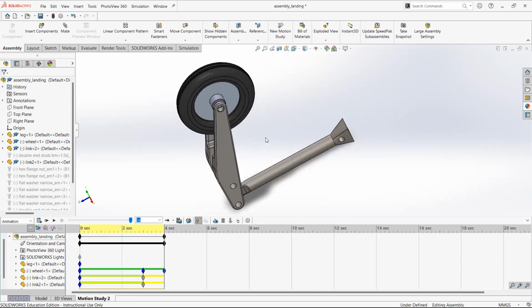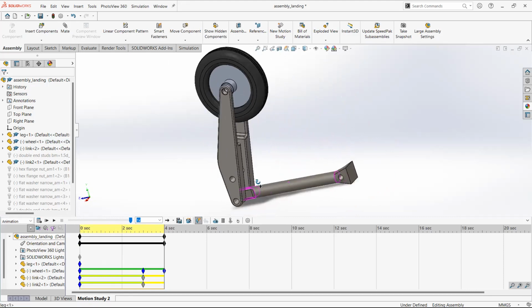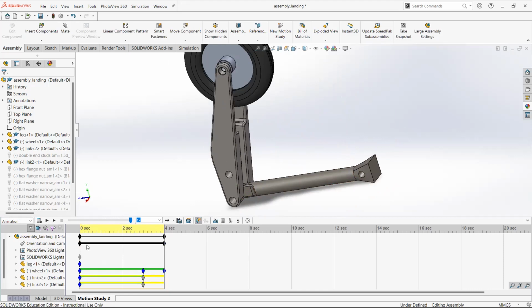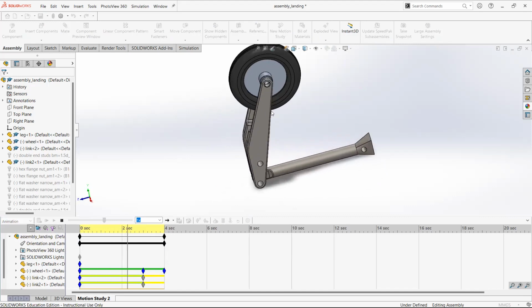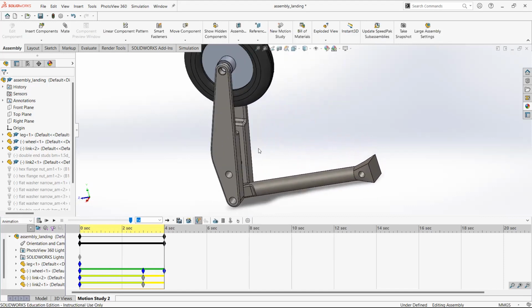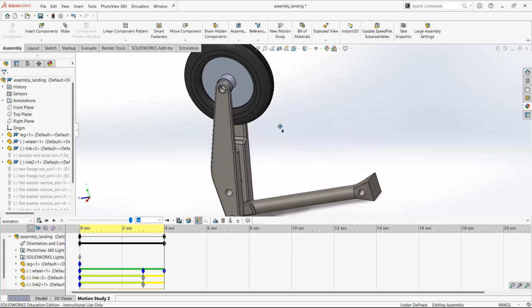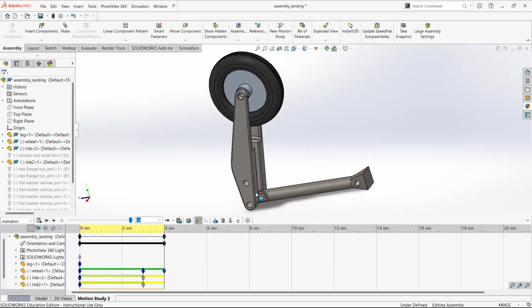So if we right click on this and deselect this, what will happen is that when we move, let's say we zoom in and we move to this view, we see this black bar, which is in the same line as this orientation. So we can know that this action would be done to this part. And when we move the wheels, we saw that this was created and those two links were created since the links were moving with the wheel. So now when we calculate our animation, as it is moving, the camera will also move, which can be used for creating various different animations.